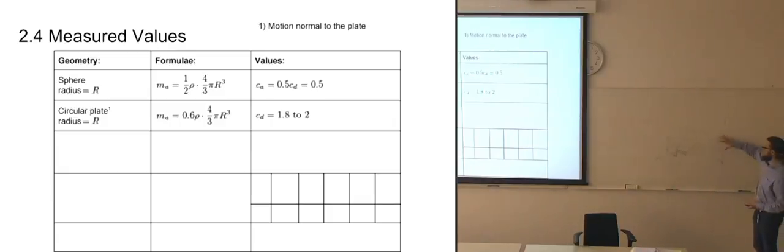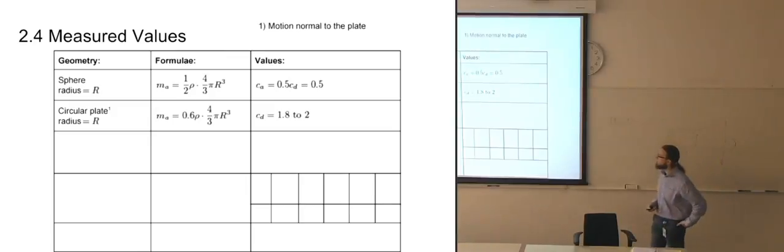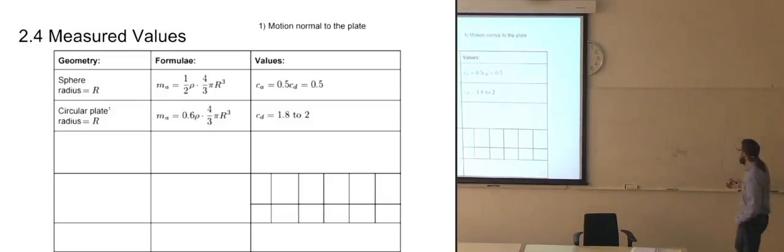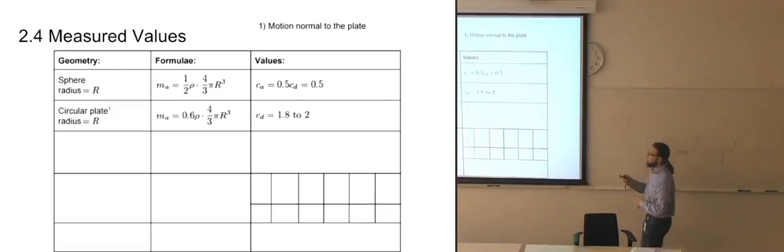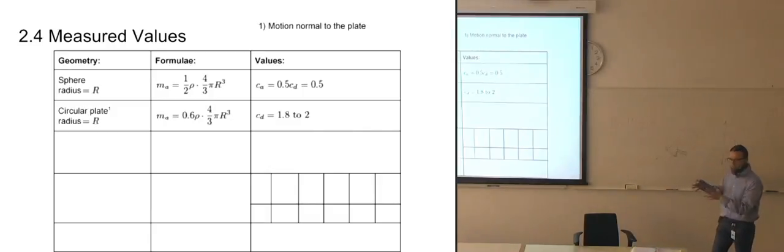So we're getting the full cross-section of the entire plate as the area. And again, we're using the basics of a sphere in order to calculate it. But instead of getting 0.5 there, we are putting in 0.6. And I'm guessing that has to do with sharp edges or something like that. As I told, these are measured values, so this is what they have calculated while doing tests on it.